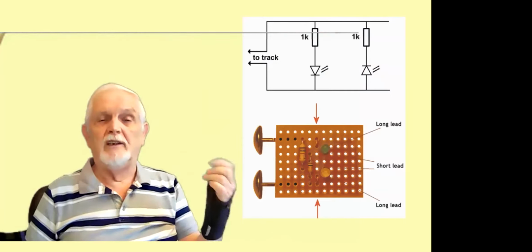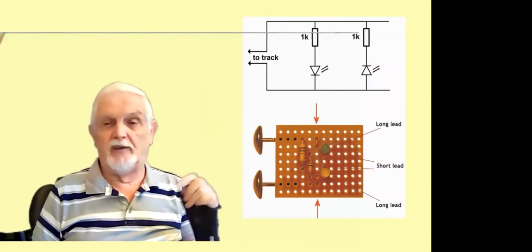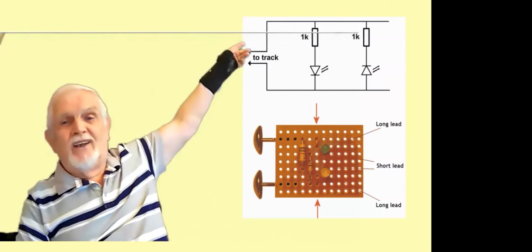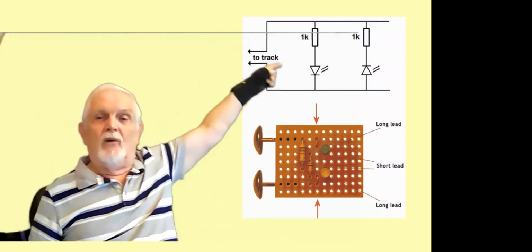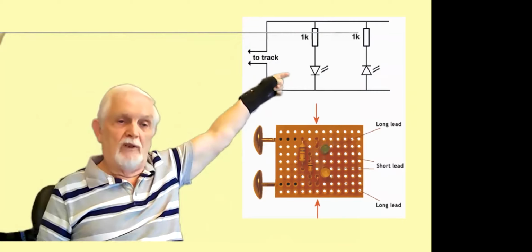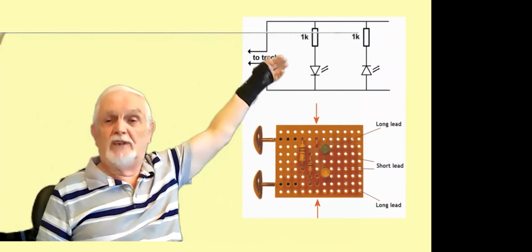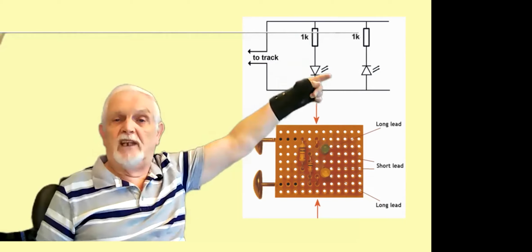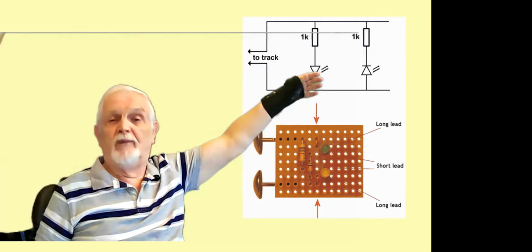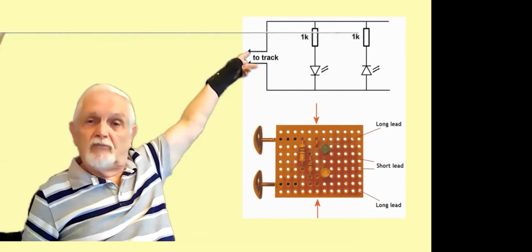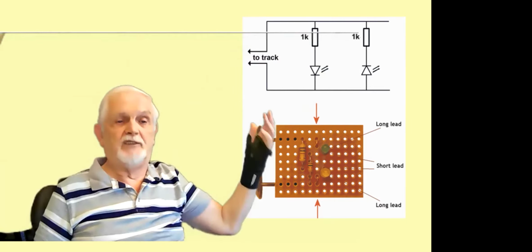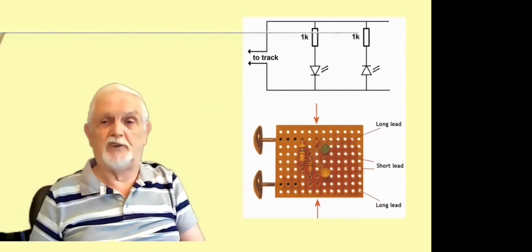We use that a lot. There's that little kit we have for the crack tester. If you put the power on one way, one of these diodes, because an LED is just a diode at the end of the day, one diode is forward biased and will illuminate. The other diode, by definition, because it's reversed, is going to be reverse biased. It won't light up. If you invert the power to the track, the opposite happens. The other one now lights and the other one extinguishes.